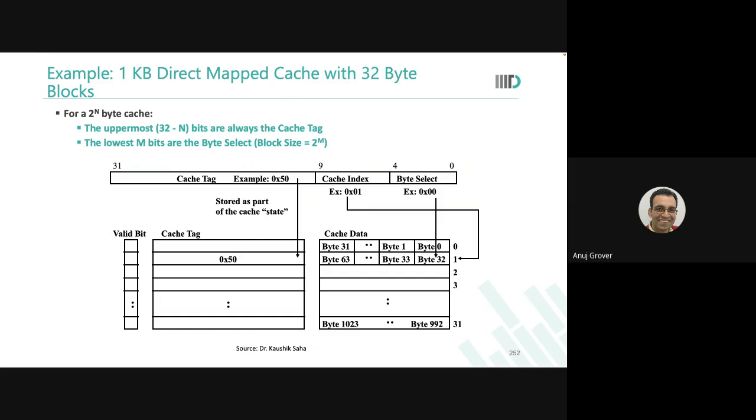For example, if you have a very simple 8-bit microcontroller, but your memory bus width is large, because it is an 8-bit microcontroller, you only need 8 bits at a time. The processor would only request 8 bits. It cannot request 64 bits. You are fetching 64 bits because your line length is, let us say, 8. So you're getting 8 words in one go, but you still need only 1 byte to be sent to the processor at a time. So this is like a strobe signal.